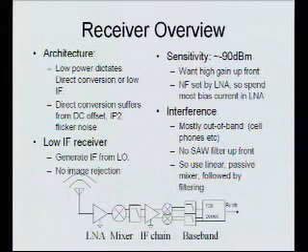You were saying something about how you can shift your image, but you can just shift it two spots, right? I mean, you can have your LO either above RF or below RF. For simple, that's the first thing you can do. But you can also, since you're deriving your IF from your LO by dividing it, just divide by a different number, and your IF changes.